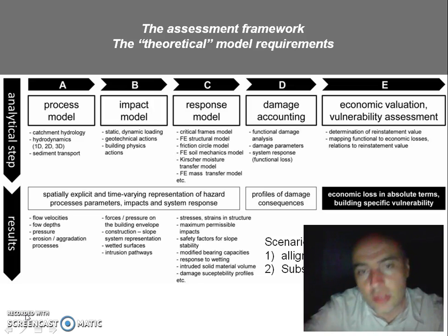If we only determine one maximum value of the stresses and strains, we might compare these maximum values with the maximum permissible values, and obviously depending on this comparison we might conclude that the structure is going to fail under determined loading conditions, or is going to resist the specified loading conditions.